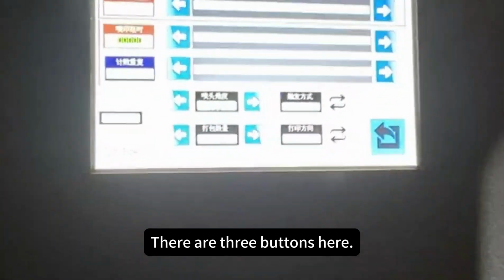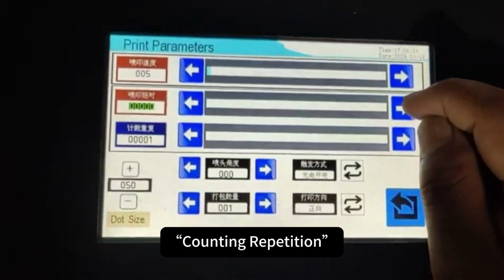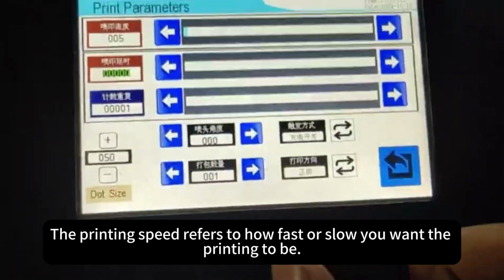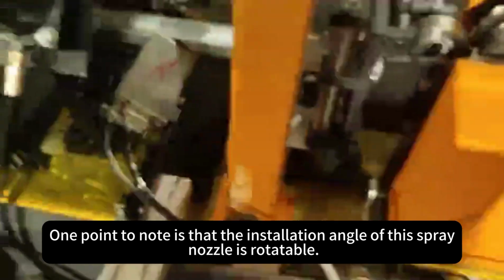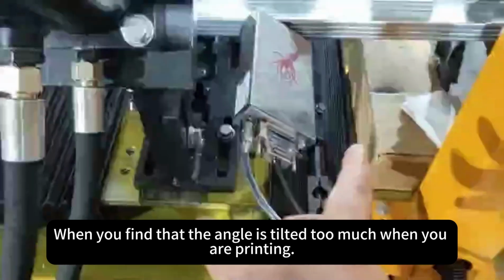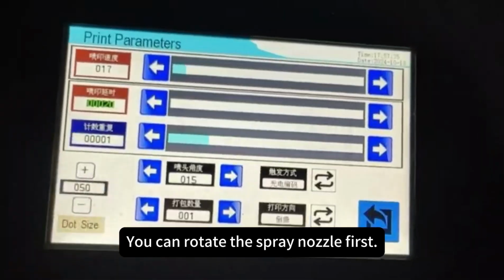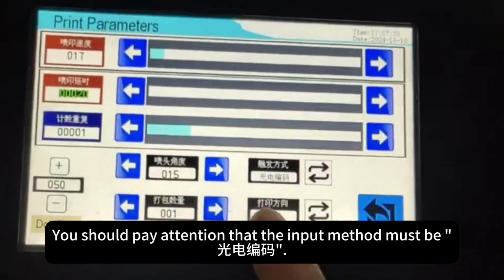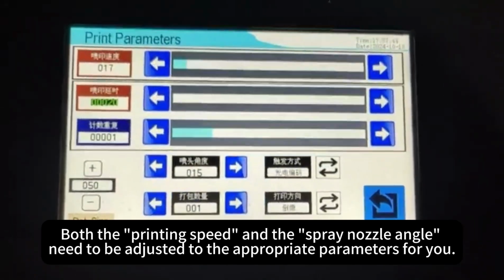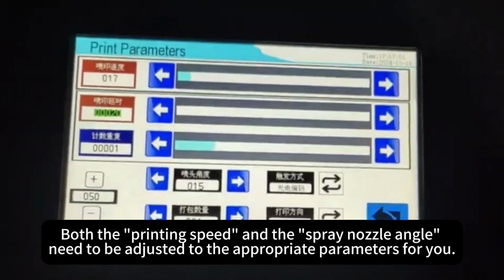There are 3 buttons here: Printing Speed, Printing Delay, Counting Repetition. The printing speed refers to how fast or slow you want the printing to be. One point to note is that the installation angle of this spray nozzle is rotatable. When you find that the angle is tilted too much when you are printing, you can rotate the spray nozzle first. You should pay attention that the input method must be photoelectric encoding. The printing direction is reverse. Both the printing speed and the spray nozzle angle need to be adjusted to the appropriate parameters for you.